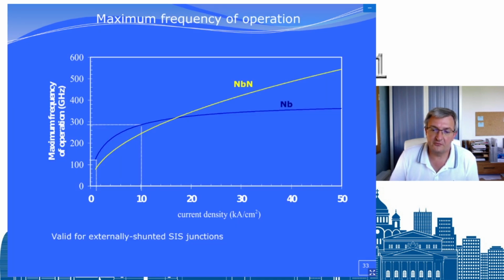I have a curve here. If you take niobium, for example, with the current state of the art, 10 or 20, you get about 300, 400 gigahertz, right? It's what you can reach reasonably. In practice, you are lower, typically 1/3 of that. So you can find today a digital circuit with 100 gigahertz clock frequency. You won't go much further away with niobium.